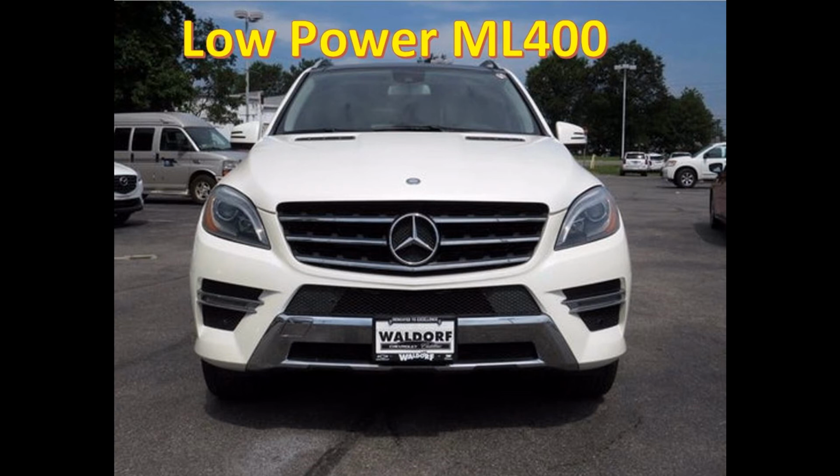So basically what's happening is the left side turbocharger isn't producing any boost, and the right side turbocharger, because of the leak on the left side, the computer is not able to control it. Bottom line, this thing's going to need a left side turbocharger to fix it. And yeah, that was kind of an interesting one. It didn't turn out to be too bad in the end, but the left side turbocharger wastegate was the culprit on this guy.